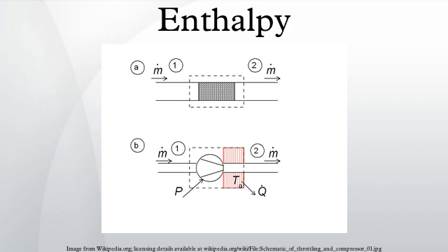Compressors. Fig 3b is a schematic drawing of a compressor. A power P is applied, for example, as electrical power. If the compression is adiabatic, the gas temperature goes up. In the reversible case it would be at constant entropy, which corresponds with the vertical line in Fig 2. For example, compressing nitrogen from 1 bar to 2 bar would result in a temperature increase from 300 kelvins to 380 K. In order to let the compressed gas exit at ambient temperature, heat exchange, for example by cooling water, is necessary. In the ideal case the compression is isothermal.